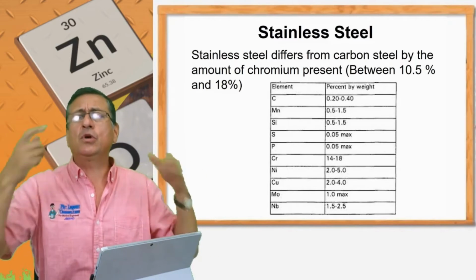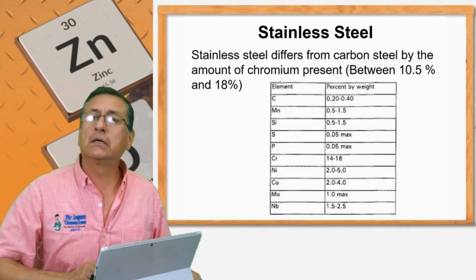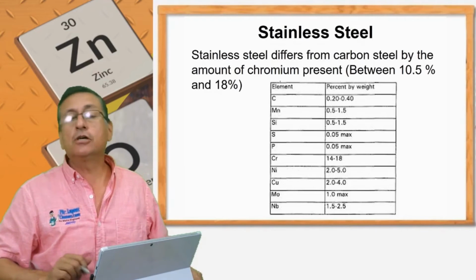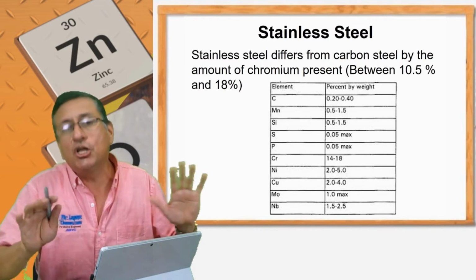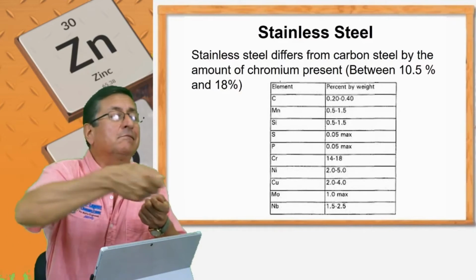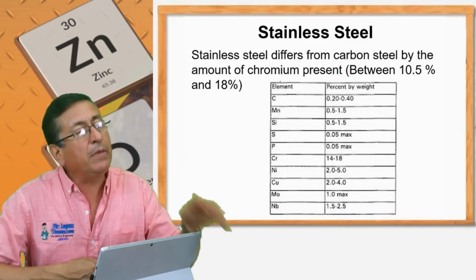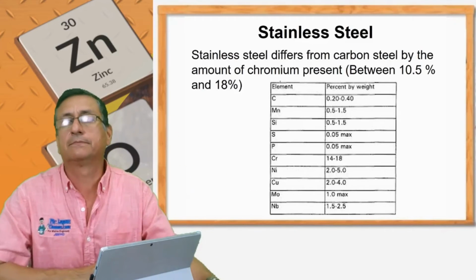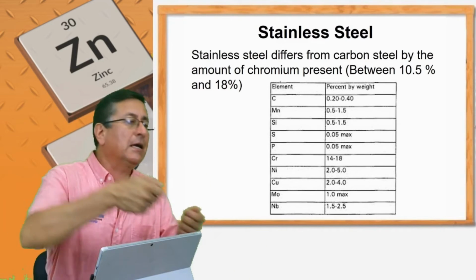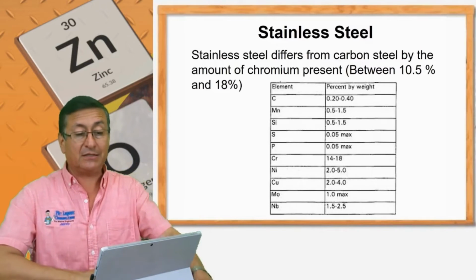Oh, this is the bracket to install the air conditioner. Okay, it's marine grade? Oh, of course. Can I check with the magnet? It's a little magnetic. That's not good. If it's a little magnetic, it's not good. It will corrode easily. Let me approximate the grinder. Oh, look, a lot of spark. That's not good. That alloy will corrode. In 6 months, it's corroded. No, it should be marine grade: not magnetic and practically no spark. Don't forget, this is a good tip about stainless steel.